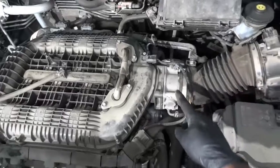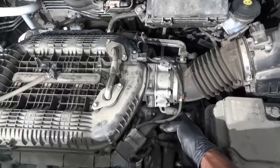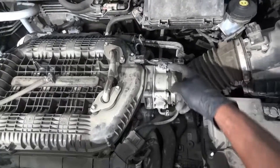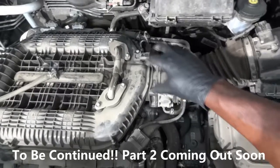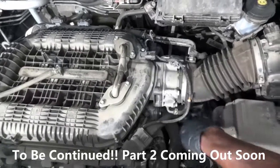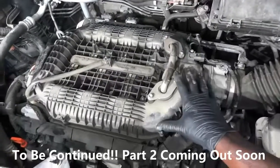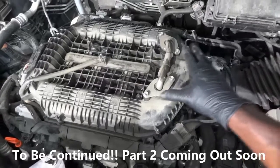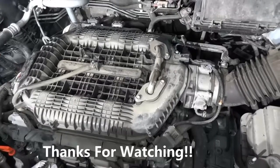Actually, the throttle has coolant lines going to it, so I'm not going to disconnect these coolant lines. I'm just going to undo the throttle and lay it down over here. I'm going to remove the throttle from the intake manifold, lay it down, and then the intake manifold is going to come out. This is really straightforward, so it doesn't take much. I'm going to set you guys over here so that we can remove the intake manifold. So let's do that.